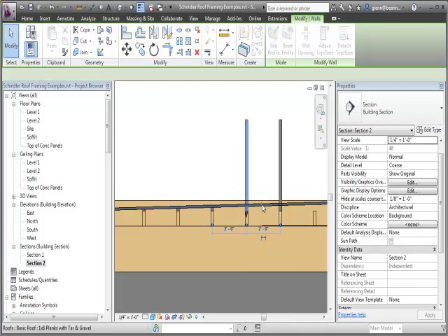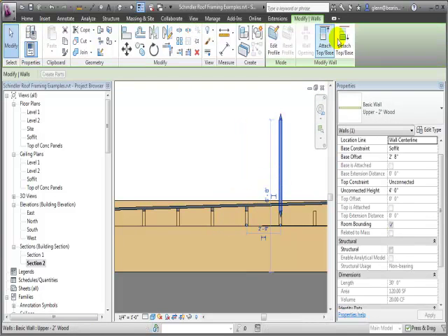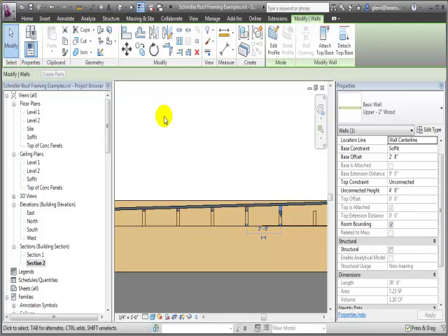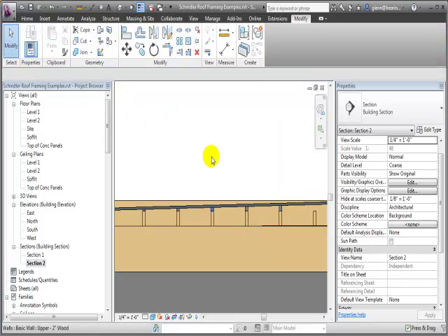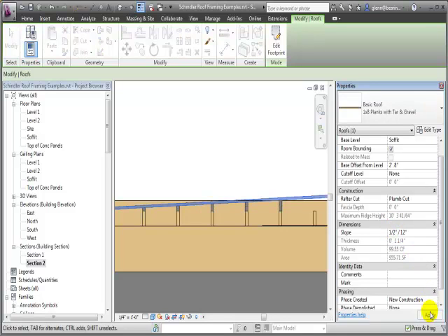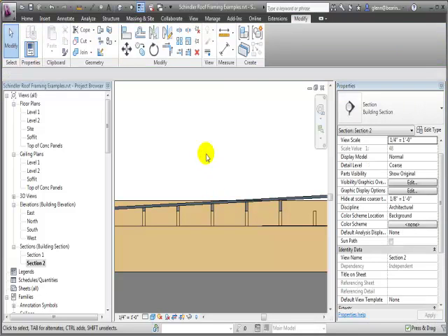Just attach them there. Again, I guess it is an accurate way to model it. It feels a little bit strange using walls to create those fill-in pieces, but it actually is an effective way of having something that's going to automatically resize and adjust. The nice thing about doing it this way is, if, for example, that did change to half, you can see they all resize themselves automatically, which fills in that gap nicely.